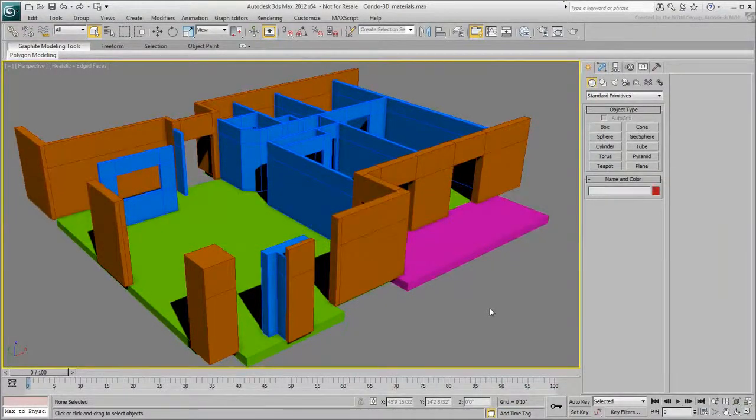With the walls and floors in place, let's take a look at how you can improve the scene by applying simple materials to objects. You'll come back later to more modeling to create doors, windows, and curtain walls. Commonly, you use the standard material for the scanline renderer and the AutoCAD design material for the mental ray renderer. In this movie, however, you'll be focusing on the multi-subobject material, which is crucial in architectural rendering.